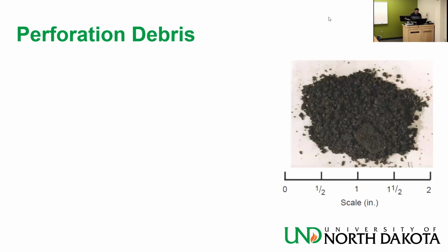Perforation debris is very, very important. Regardless of what technique you are using, you have to deal with it. So you need to either dissolve it or remove it mechanically, or you don't want it to block your perforation tunnels. Now, the perforation tunnels are narrow. They can be blocked very, very easily. So be very, very careful.